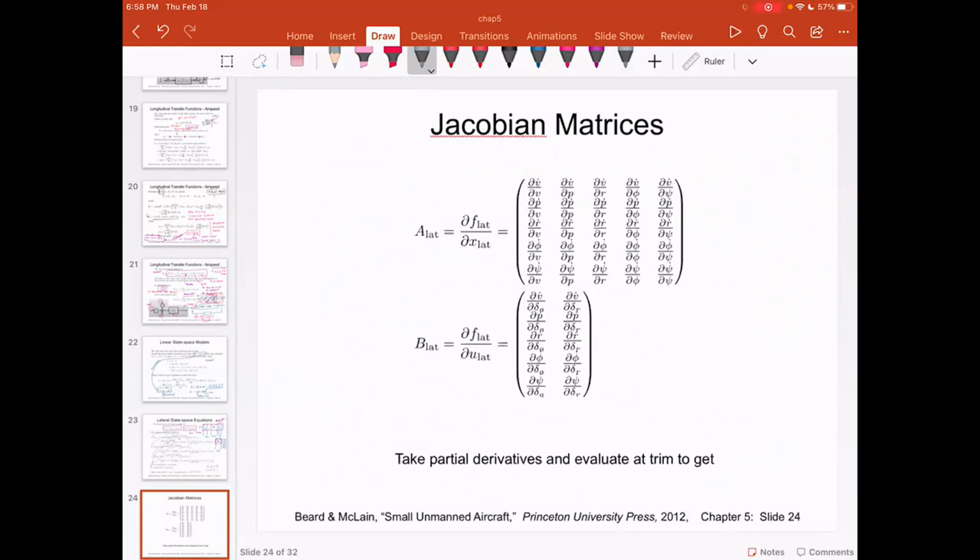Remember, in Robotics 1, when we looked at the equation for position of the end effector, I had xp, yp, zp. And then we used the Taylor series expansion and the Jacobian for linear velocity, and we used the Jacobian for angular velocity.